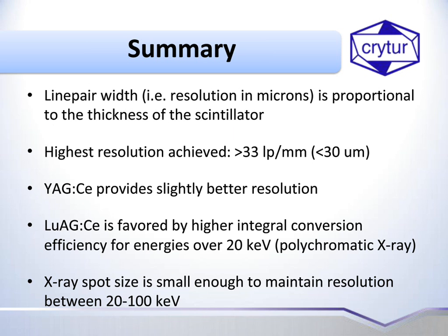And also, we actually confirmed that the X-ray spot is small enough to maintain resolution between 20 to 100 keV. As I said, the X-ray spot was about 1 micron, and the resolution of the system is more than 1 micron, so it means that the X-ray spot didn't play any role in that.